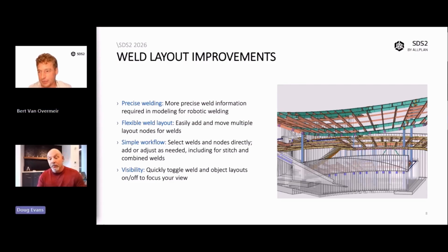With weld layouts, so we've improved weld layouts in 2026 as well. With the advance of all the robotic welding machines and all the things that they need in codes and things like that, we've added things. So we've increased the precision on our welding. We have start and stop points and easier to add and move welds. And so you can select welds and create nodes. Again, being able to commute that automated fabrication process, that's really going to help with people that have invested in those 3D automatic machines that automatically weld steel. So I know those have been some good improvements in weld layouts in SDS2 in the model.